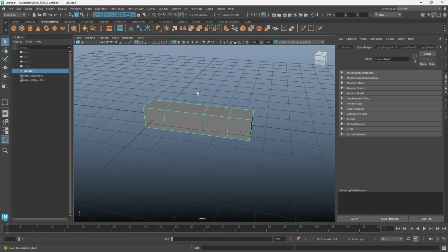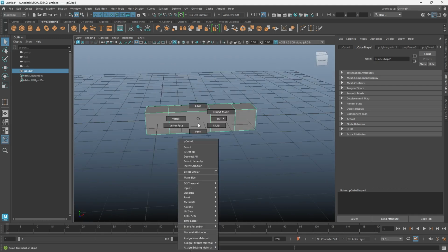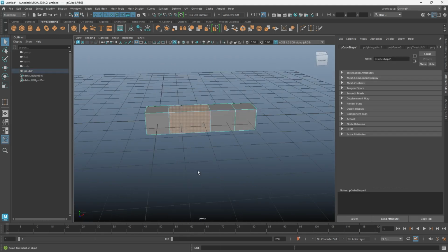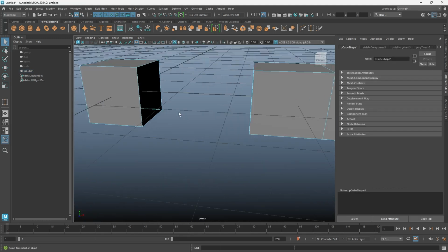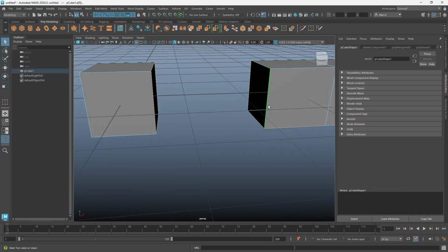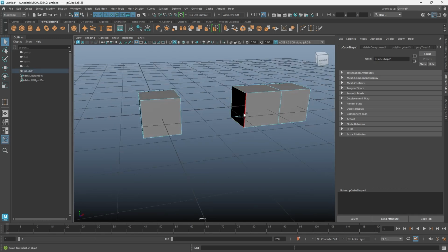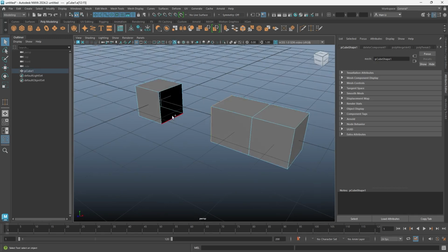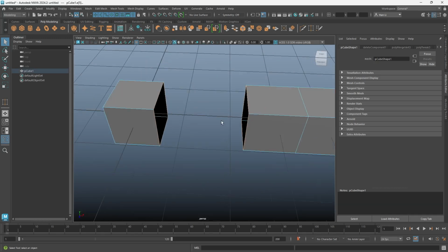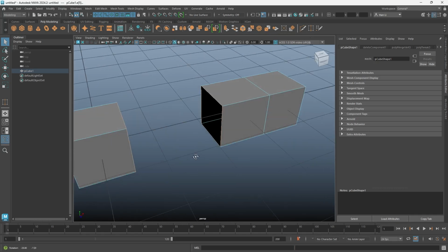Okay, next let's showcase the bridge tool. Let's say I delete this right here, and I want to connect these two together. So I would select this and just select this. Ooh, I don't select them. Do this. Here we go. And then let's do the bridge tool, which is this one right here. It looks like a little bridge. If I select it, both sides of the edges must be a closed loop.